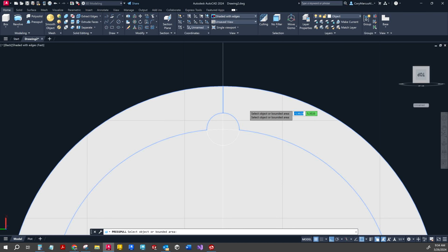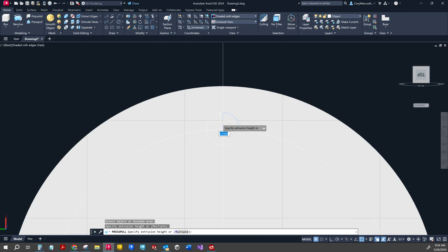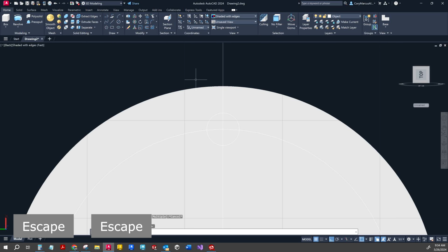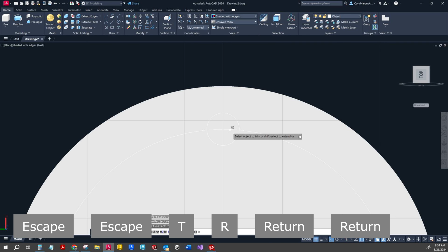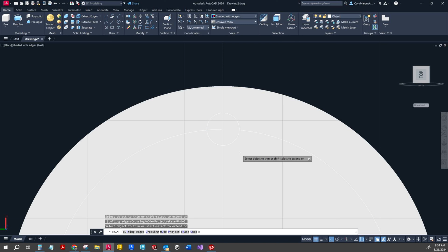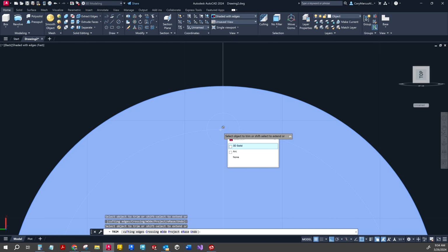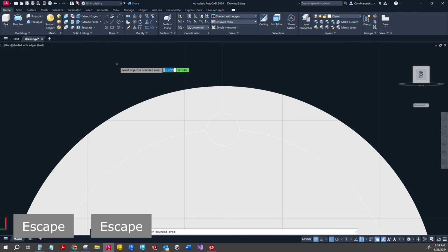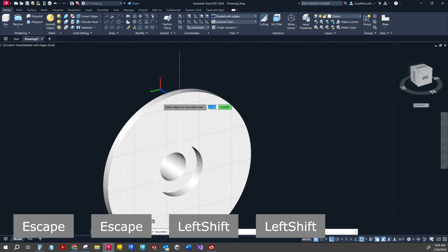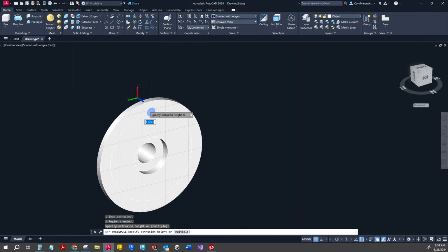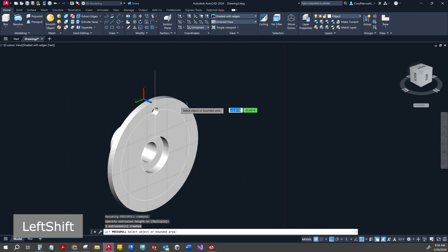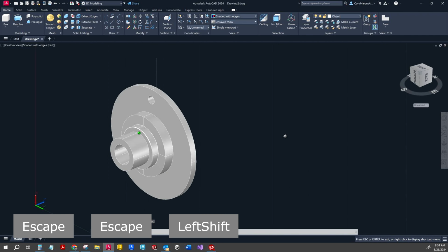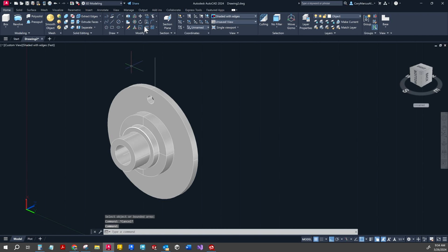We'll go ahead and just do a press pull. That's right. Okay, so we're going to trim. And one more. There we go. Okay, so now we'll do a press pull. I'm just going to pull it out, and it cuts it. So now we've got our hole, and we can do a polar array.